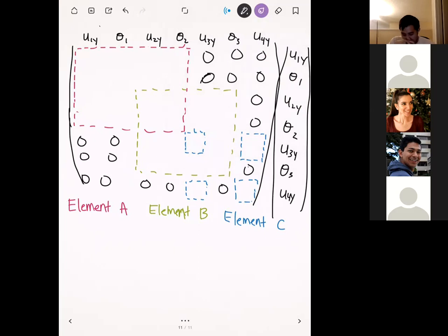Okay. All right. And so now that we've assembled the matrix, now it's time to apply boundary conditions. But since this problem is going to ask us to solve for the reaction forces, don't throw this matrix away, okay? And so at this point, we've included all the element stiffness matrices. We just haven't applied the boundary conditions, but we're going to use this same matrix here to compute the reaction forces. So save this matrix. Okay.